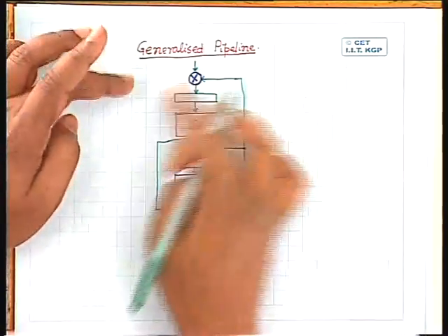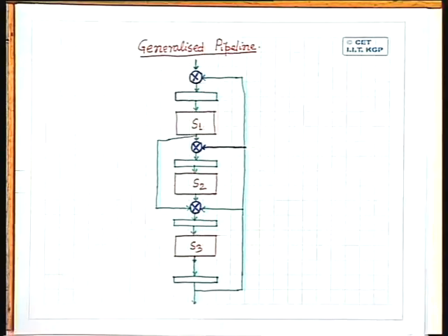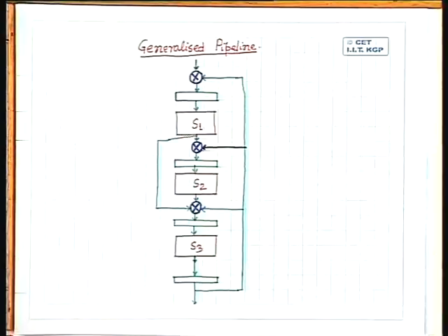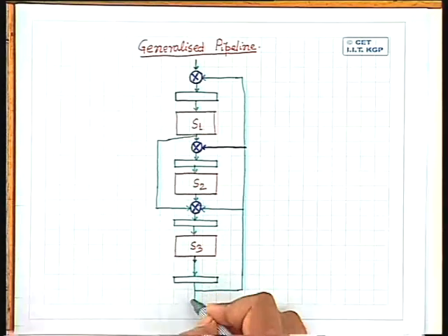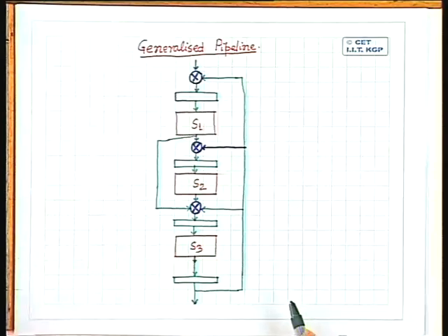Okay. So I have a reconfigurable type of pipeline. Depending upon the function requirement, I can choose these multiplexer select inputs so that the data will be routed through this pipeline as required. This can be used for computing a single function. It may also be used for computing multiple functions, that is, more than one function can be computed by the same pipeline.